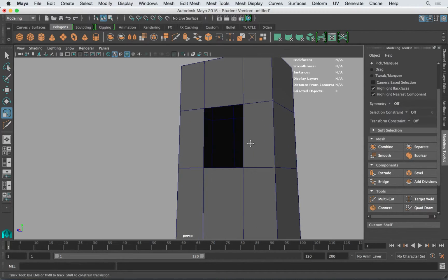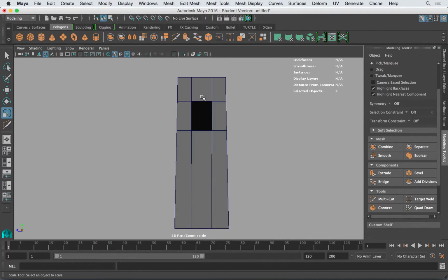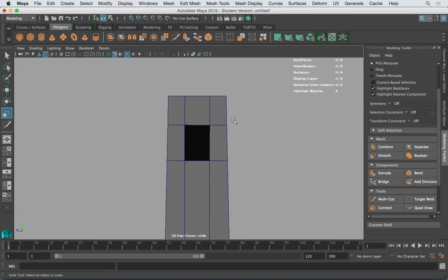So what I'm going to do is go to my right view. Anytime you want to open a shape on another shape, like punch a hole, you use a template, a guide. The easiest thing to do and the smallest is to use a cylindrical shape, but with a minimum amount of subdivisions that looks like a circle.